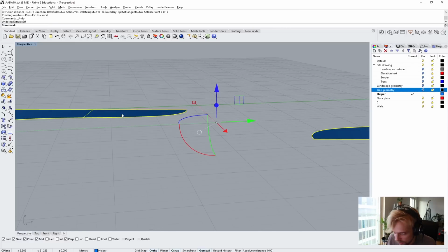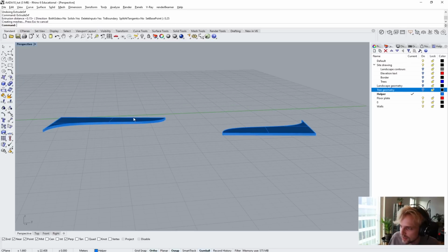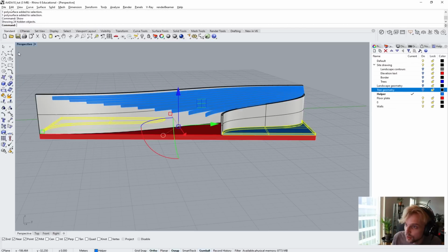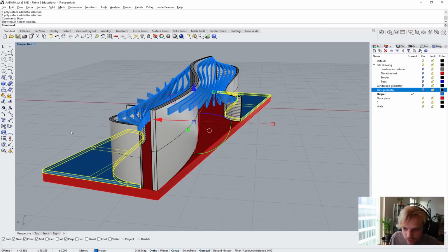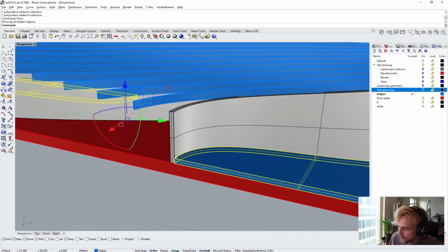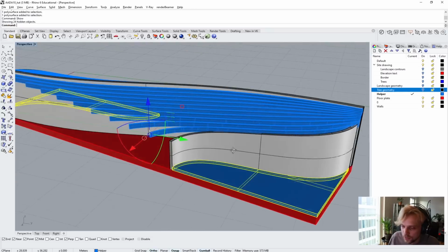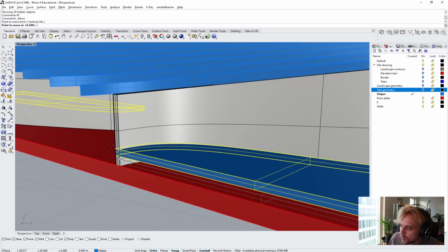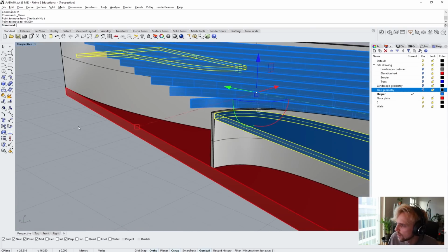That's a bit, no, 0.25, like 25 centimeters, I think is a bit better. Right, let me unhide or unisolate everything. And then while I still have these two surfaces selected, I will take them, move them up until they meet this point right here. It should be correct on the other side as well.